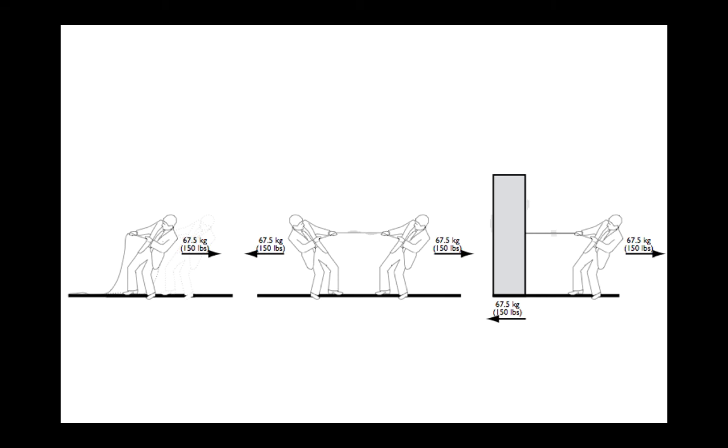Now, stress is really important. We think about stress usually as kind of a bad word, right? No one likes to be under stress. But it's the mechanism by which structures can actually be made to work. In other words, stresses we can think of also as a capacity, right? An ability for a material and a structural element to resist those loads, to carry those loads. And we'll talk about the ways in which they do this. They only do it maybe 4 or 5 different ways, and we can take advantage of those to develop load paths throughout a structure.